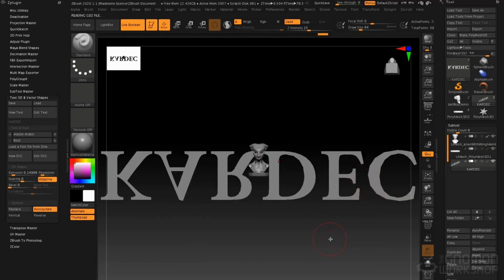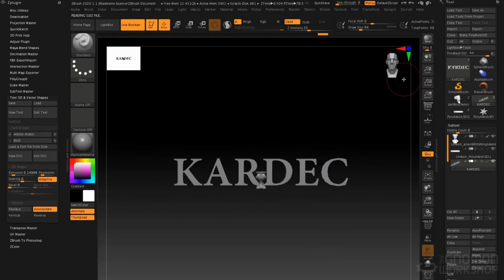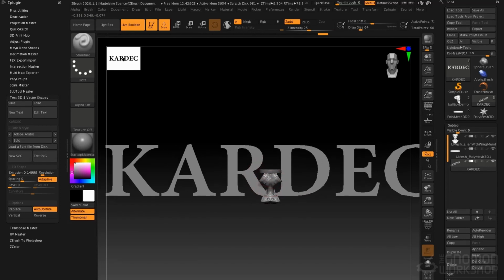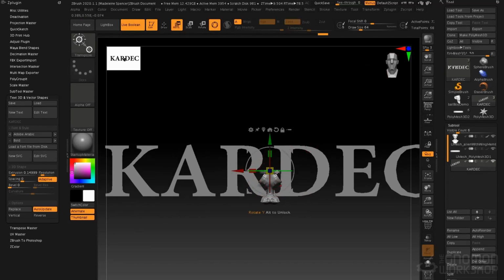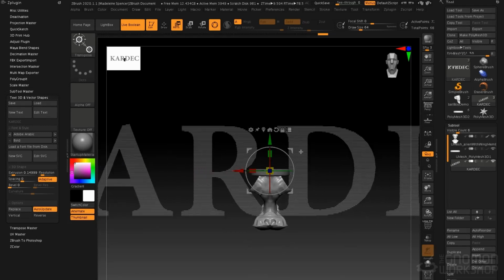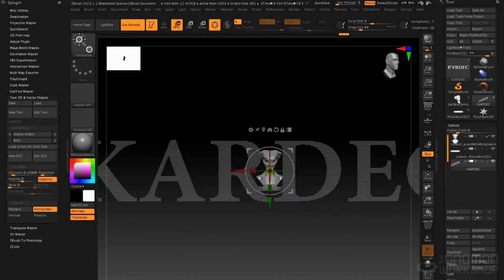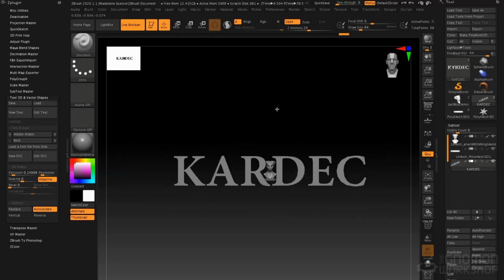Let's press F for focus. Here we can see it's actually rotated because our character is actually rotated incorrectly. So I'm going to fix that by going to the Transpose gizmo and turning on the pizza box stack there, and I'm just going to invert my selection by Control-Shift clicking on that, so only the bust and the base are now selected. Then I can easily do a snap rotation around 180 degrees and bring him here so he's facing the same direction.